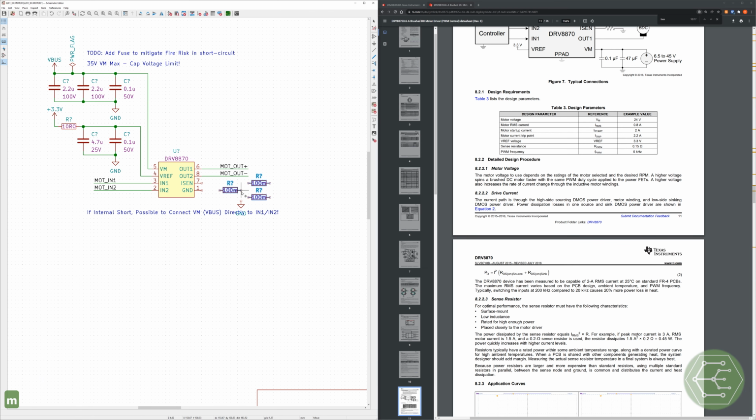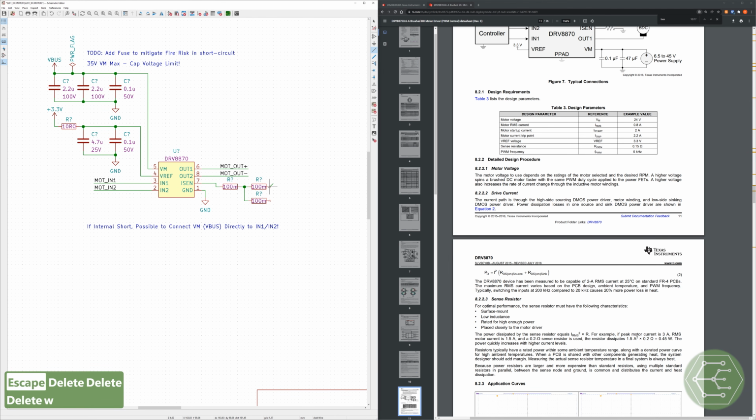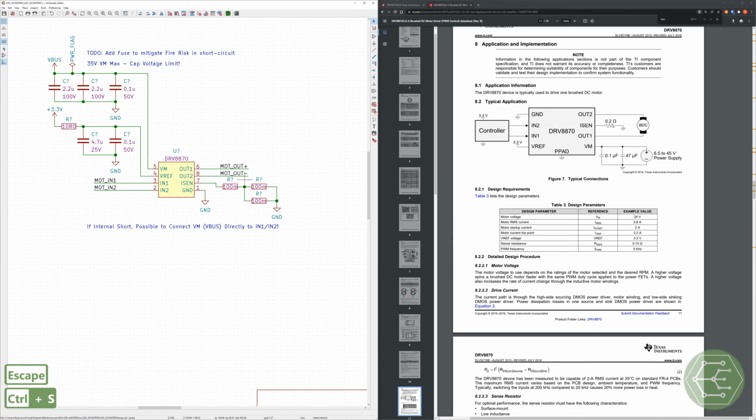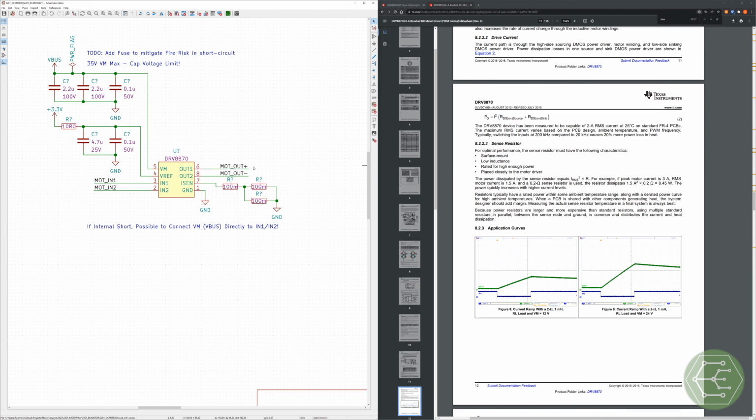I'm going to make my 150 milliohm resistor. I think you can see where this is going. There we go. Get these in parallel. Oh, look at that. And then we'll drop off our second ground reference. I'm guessing that some kind of filtering might make sense. Putting a cap off of I send to ground will probably help it to work just a little bit better, take some noise out, but that's a pretty low impedance shunt, so yeah, we'll see. So this would be a 2 amp current limit.